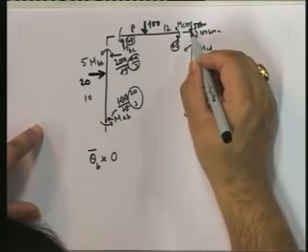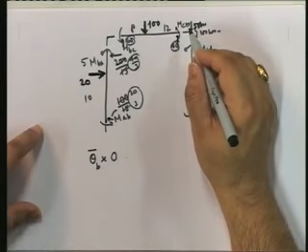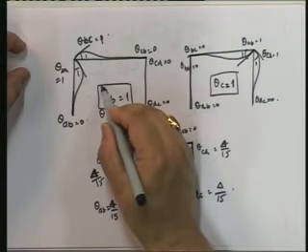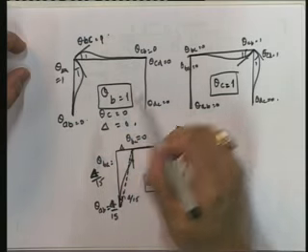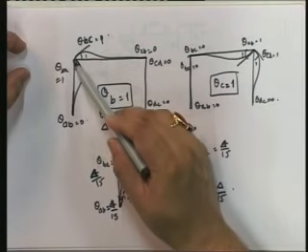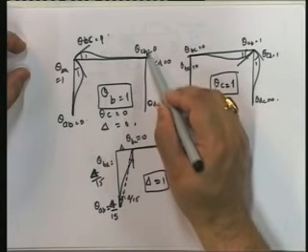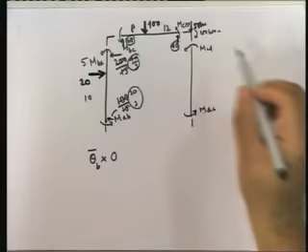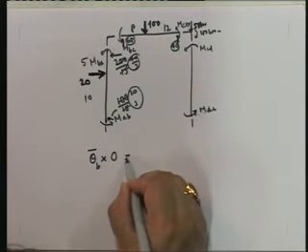So how much does this joint displace by under theta b? Let me look back at the equation that I have drawn. See, this is my theta b, and now I'm giving this a virtual displacement. So I'm going to have this into 1, nothing, 0. This is not going up, neither is it rotating. So these two don't do any work. Okay, so the external virtual work is equal to this.